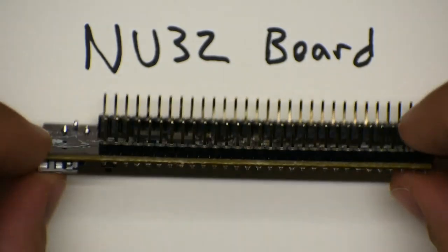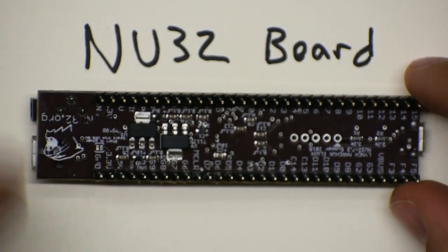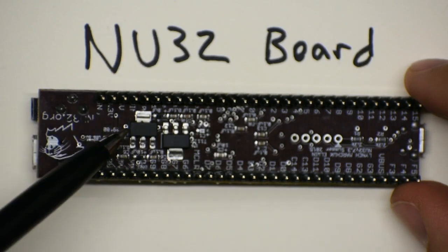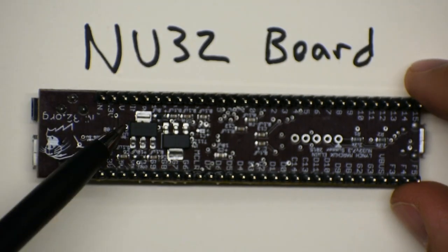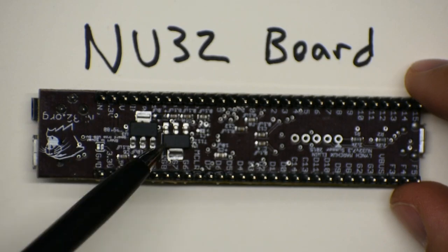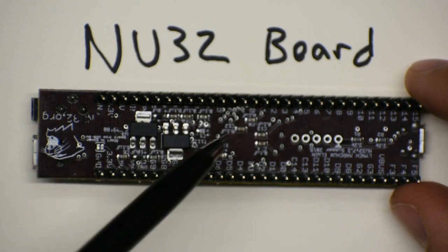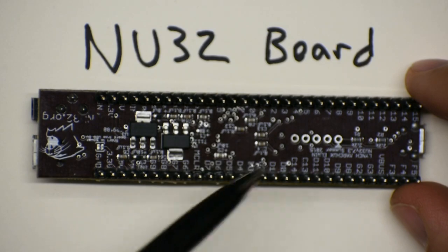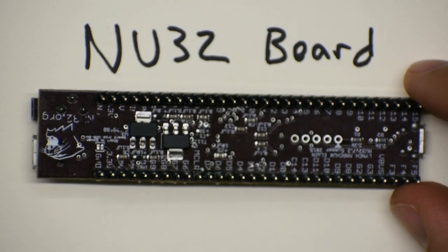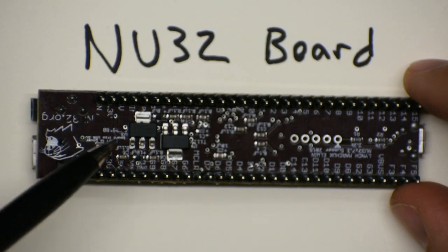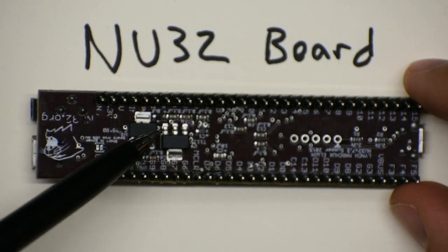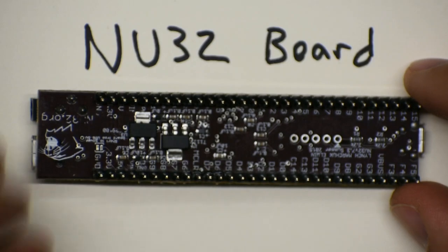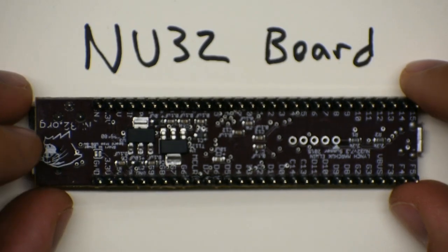So how does the power system on the board work? We'll flip it over. And we have two voltage regulators on the bottom. One takes the voltage in from the DC jack and makes 5 volts. The other takes the 5 volts and makes 3.3 volts. And then the PIC is powered by the 3.3 volts. And most systems that we use nowadays run on 3.3 volts. Now, traditionally, 5 volts was very popular, so we still provide 5 volts through one of the pins. And someday 1.8 volts will be standard, so things are constantly changing.